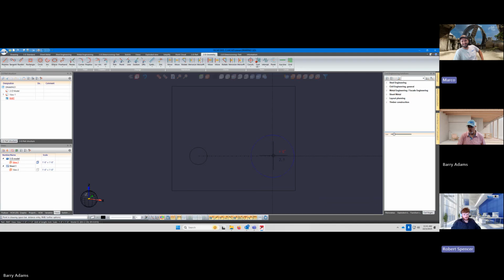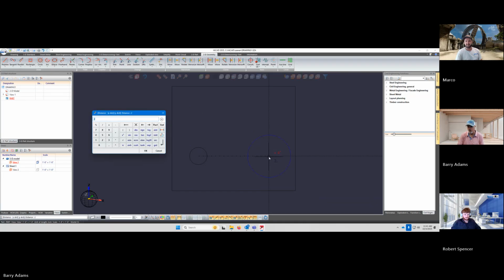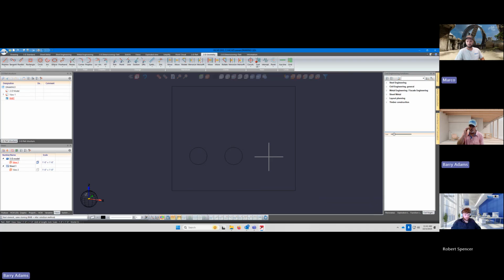Let's just drag it in the right direction here and hit spacebar. Now just give it a 1 inch. A 1 space 0, although I think you could probably leave out the space 0 here, but just try 1 space 0. Okay, and see it moved over.